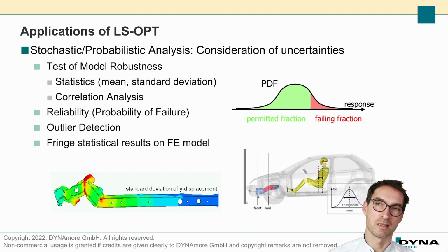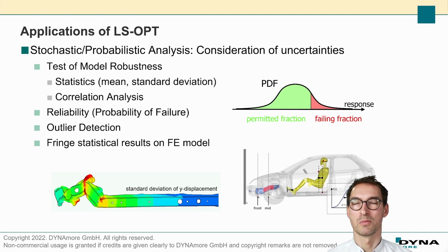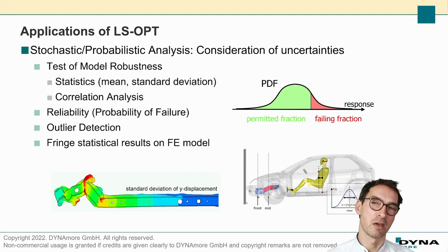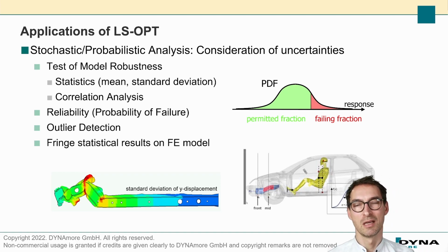For instance, let's say you have a sheet metal and your supplier tells you it's not 1 millimeter all the time, it's maybe 1.1 or 0.95. If you take this sheet metal with a higher range of fluctuation and make you a lower price, then maybe at the end of the day you can save money, because you're accepting this lower price knowing that the outcome of your result is not fluctuating so much with this change of parameter. So this actually helps.